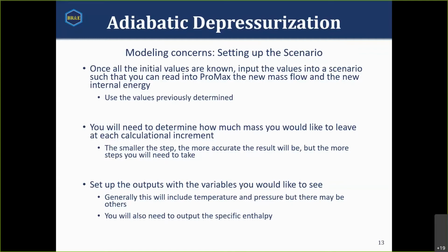Again, we do have a tool that will help simplify this and will calculate reasonable step sizes. For the purpose of understanding the theory, we are going to be doing this. When we're setting up the outputs to our scenario, you do want to set up the outputs you're going to want to see. You will need to output the specific enthalpy for the purpose of calculation, but we are going to want to include, in most cases, things like the temperature, pressure, and anything else that you find would be interesting or useful to you.